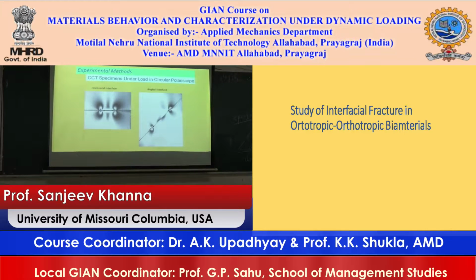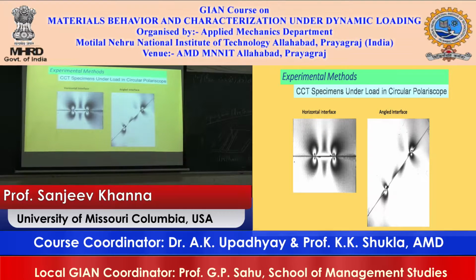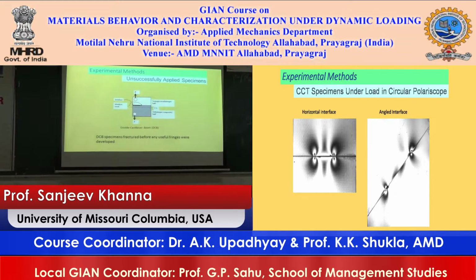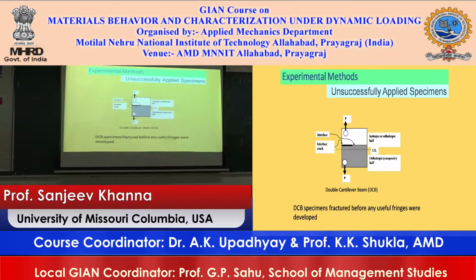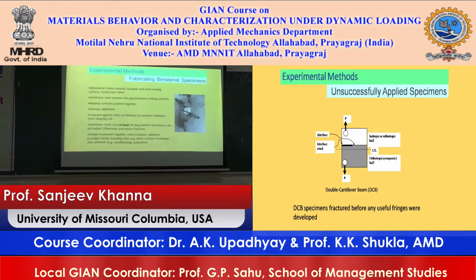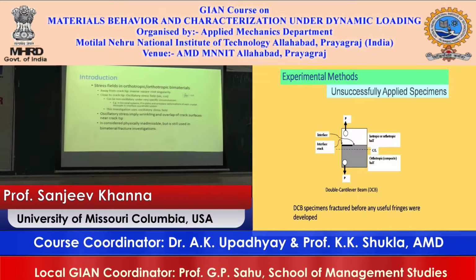If I'm now pulling it in the vertical direction, these are the crack tip stresses you see. This is at an angle. I see these stresses at the end. What you see here is probably due to some rubbing, creating some stress there. So this is the type of sample that I have: an upper half and a lower half. You join one part of it with an adhesive and leave a crack, or an unbonded region. Now to find these stress fields, what do I need to do?